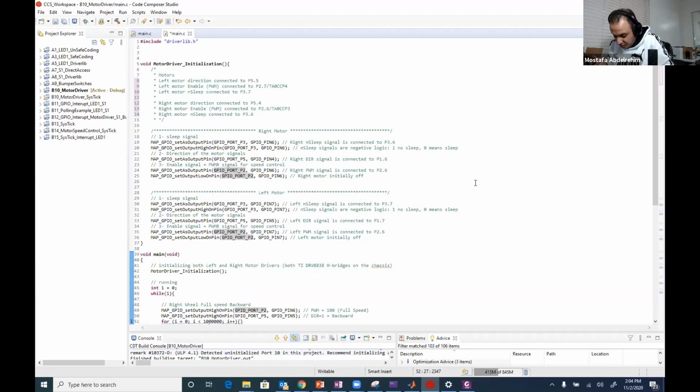Guys, remember if you're gonna buy Energizer batteries, buy the one that is 1.5. This is 1.2. I don't know if you can see this. Okay, it works, but some LEDs on the chassis board itself will not work. But it will run the motors. So if you're gonna buy Energizer, look out for this. Buy something that is 1.5, not 1.2, like this one.